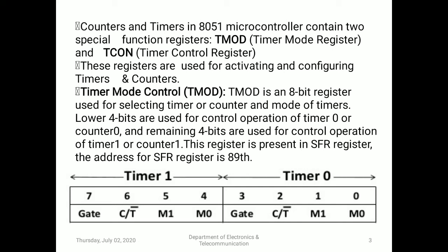In most cases we are dealing with timers, that is we are using the internal clock source, as it doesn't require any kind of synchronization circuits. And if we are using an external clock source, in that case we need to synchronize the external pulses with the internal pulses so that your operation moves smoothly without any malfunctioning.